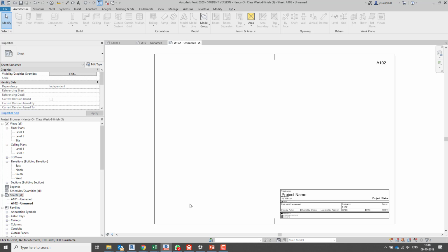No, because what's happening is that you need to go to Fronter, download it to your machine. After you download to your machine, you load it into your project. And then you say okay. Because Revit is not looking in your downloads. Does it make sense? You need to load that into your project.